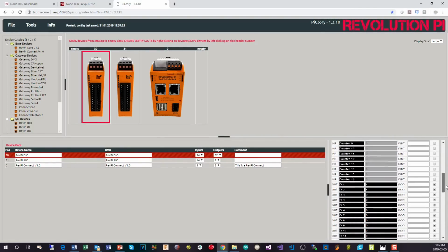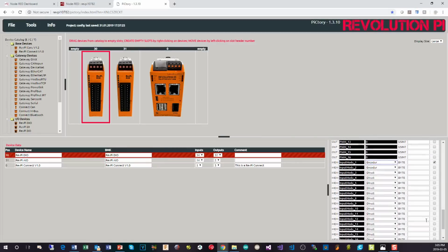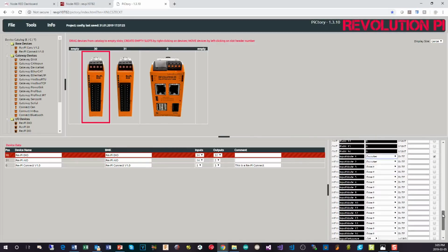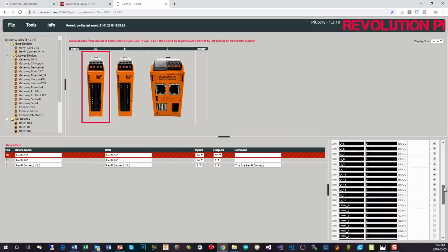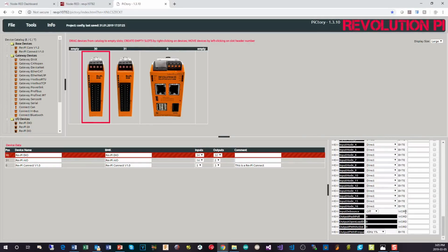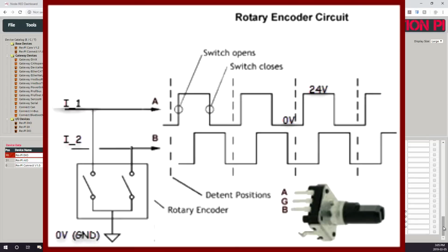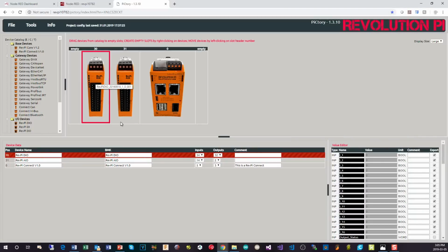I think the outputs just automatically become PWM if you write to the PWM. So I'll have to experiment with that in a separate video. I haven't really played beyond the outputs being a direct output at the moment. Anyway, what we're interested in right now is the fact that we've set that up for an encoder for the digital I/O module in this case.